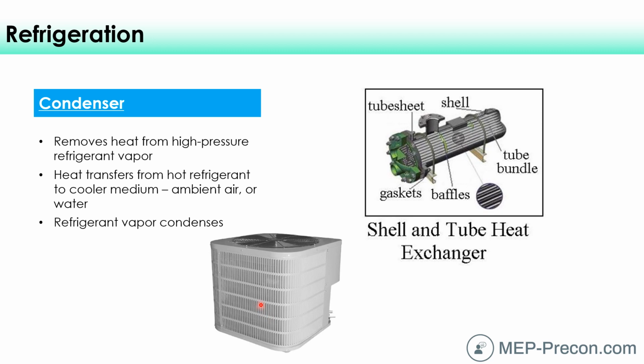Now you could have a condensing unit, essentially, which is a water to refrigerant. In fact, we'll talk about this in a couple of slides when we talk about chillers. So within a water-cooled chiller, we're going to exchange heat from the refrigerant, not to air, like within this air coil type device, but within a shell and tube heat exchanger. Within a shell and tube heat exchanger, there's an outside shell and then a bunch of tubes inside. And typically refrigerant flows inside of these tubes. It might come back in a couple of passes perhaps. And then the water flows up and down across these tubes.